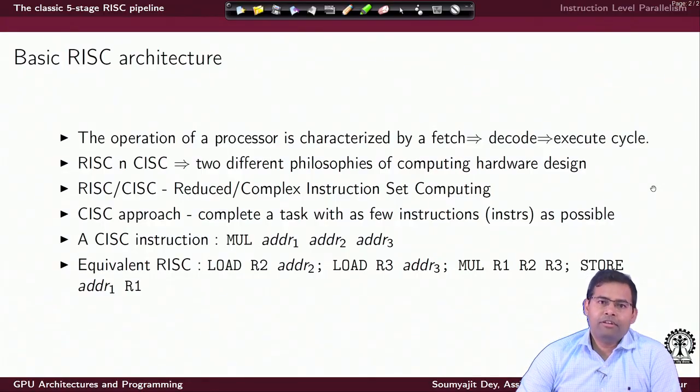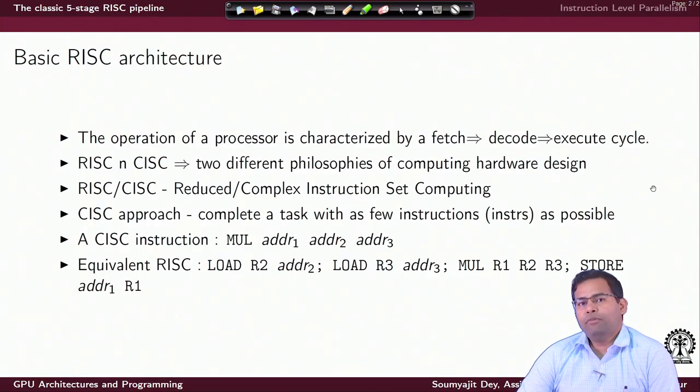To get into that, let us just touch upon what a processor really does. A processor is a digital system which is executing a few specific operations in a loop continuously. A processor crunches instructions, which we know from our basic background as assembly instructions, which are assembled by a software called an assembler into machine instructions. A processor processes such machine instructions through a standard loop of fetching the instruction, decoding the meaning of the instruction, and finally executing the instruction, and then again jumping to the next instruction.